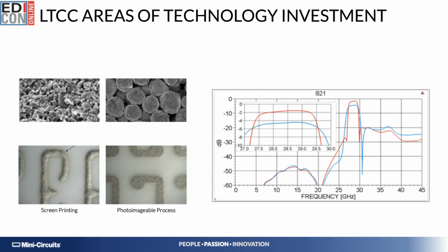The emphasis was primarily on the engineering of new material systems, mainly powders and conductive pastes, along with the development of a photoimaginable paste etching process which delivers a much improved fidelity on the layout traces. We also discussed how these new material systems enable the implementation of much needed transmission line based topologies, including distributed edge and broadside coupled structures and SIWs, substrate integrated waveguides.